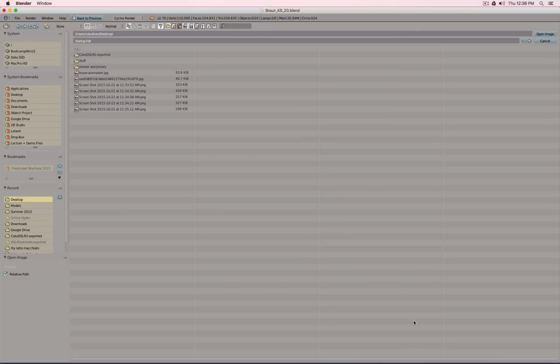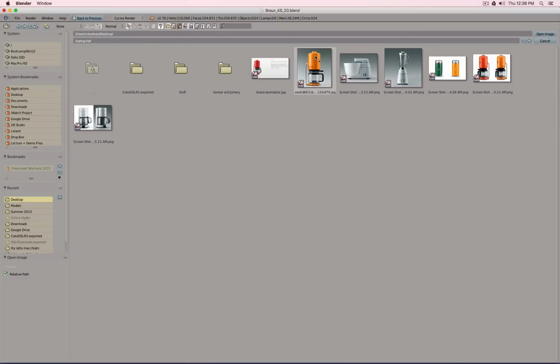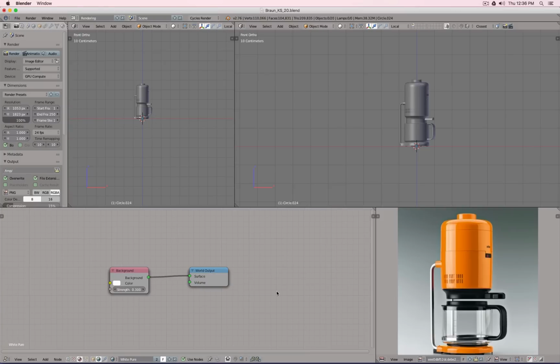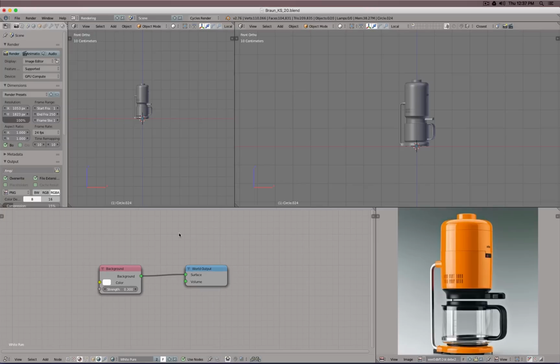So here I will load that reference photo we have there, because this really helps now when I do a rendering. I can always compare, and then I adjust my lighting, my scene settings, my materials, till my rendering starts somewhat to match my photo. Easiest way to learn it. So let's actually set the world to 0 because I would like to have a blank or black environment first, and then we will place lights.